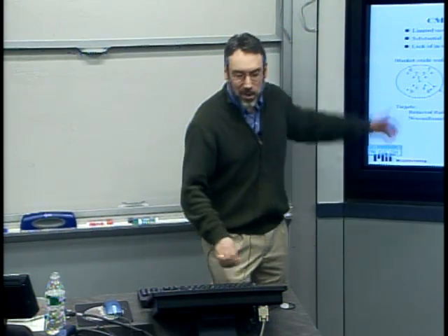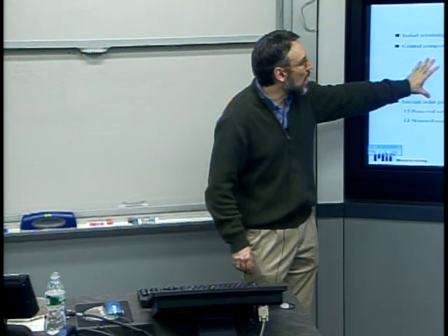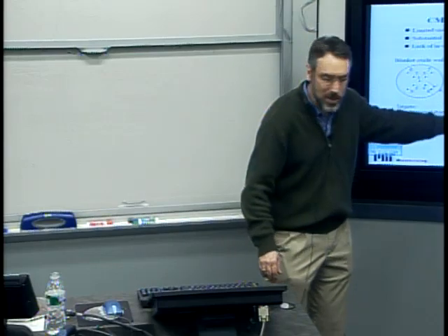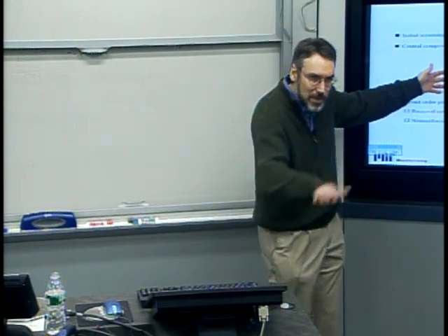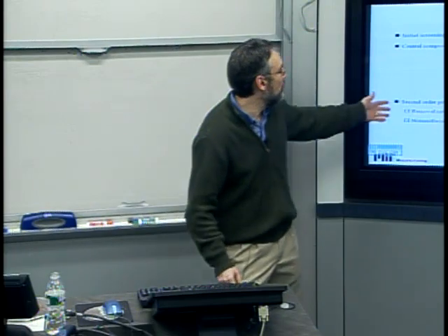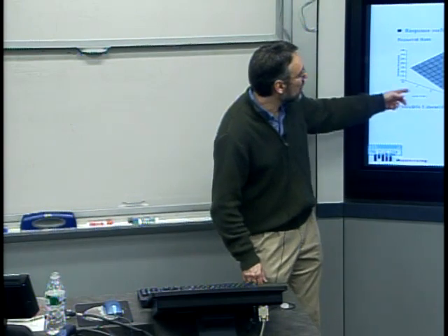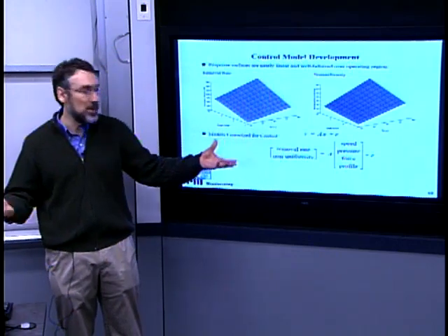And then the last thing I've already alluded to, but coming back to the CMP problem, we also can develop, and we'll talk about, response surface or empirical models that say, okay, here's what the removal rate is, or the non-uniformity is, as a function of some of the process conditions, like the speed of rotation, or the pressure or downforce of rotation. And once you have a basic control model, for example, the normalized removal rate is a function of downforce and speed, I've got some input-output empirical relationship between these.